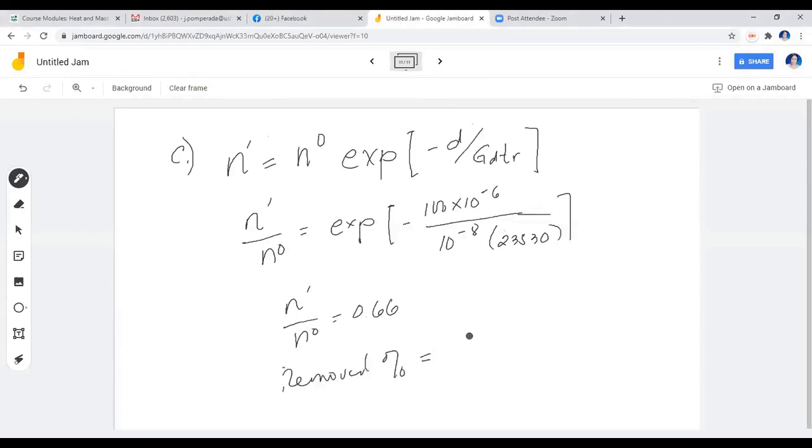percentage is equal to 1 minus 0.66. This you were able to account. So meaning the one that you were not able to account is the one that were removed already, because they have already grown to the size of 100 micrometer. So this formula accounts for what is inside the crystallizer. Now, the one that you're not able to account is the one that was removed already.